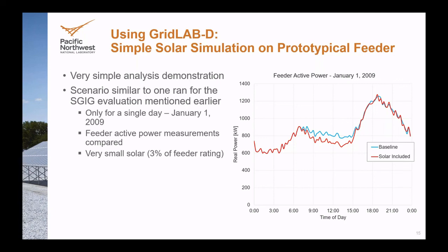And as that goes throughout the course of a year, you may see more and more differences, or you might see some type of secondary effect at 3 o'clock in the morning. It's not as important for this photovoltaic study, but for a lot of your demand response, that can be very important when you're doing peak reduction, but you end up shifting your peak to like 3 o'clock in the morning, where you're expecting your transformers to cool down and get some kind of mechanical relief, but maybe you're not having that anymore, and it actually shortens their life.